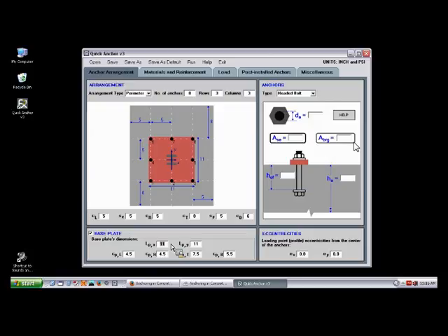But if you want to change them, you can always do that. But just make sure that, let's say, what you put as the length of the base plate and what you put as the edge distances, they kind of match with what you have with the anchor arrangement. Like in total, the sum of the base plate length, the base plate right edge distance, and base plate left edge distance should be equal to the length of the concrete that you can calculate from the anchor arrangement from above.